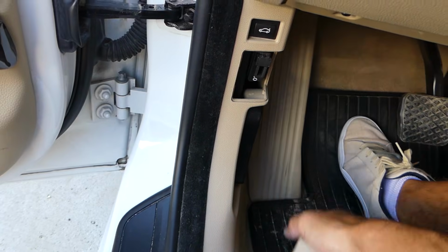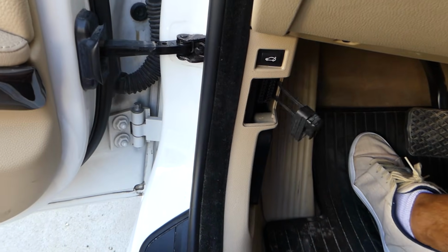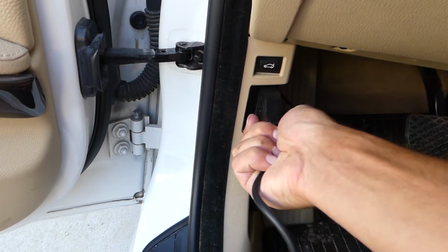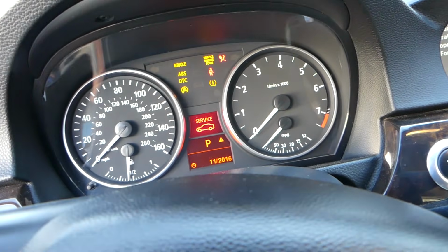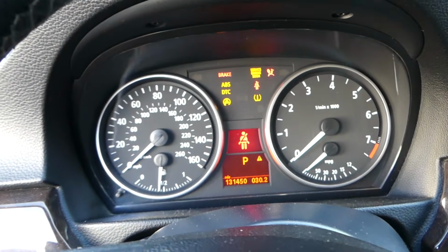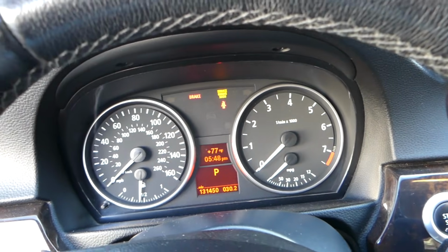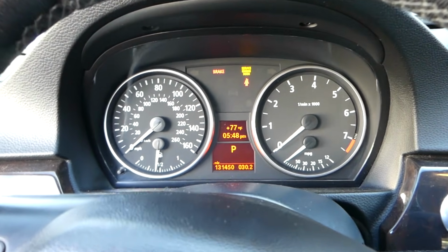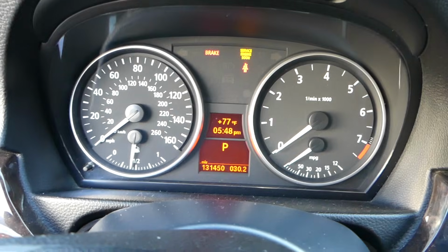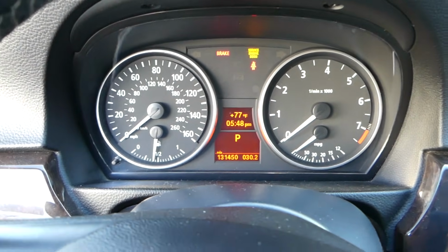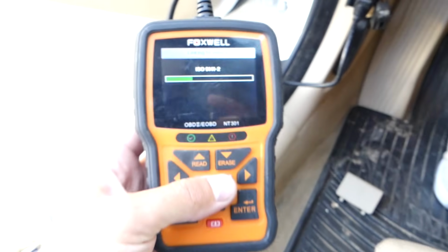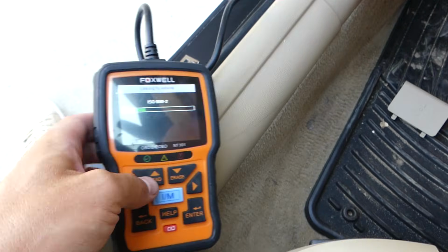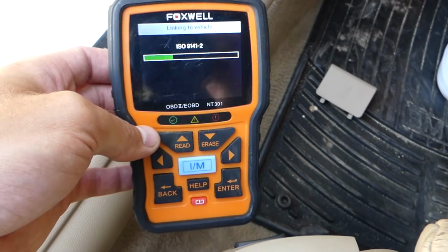So I'm going to go ahead, connect the OBD reader quick, and I'm going to reset all the codes now. Okay, we have to have the ignition on for that without the engine running. Okay, perfect. And see guys if the code will come back. So we'll definitely keep you updated on that. We're going to go ahead and drive it, and before we finish the video we'll let you know if that worked for us or if it didn't. Hopefully it will. All the tools and parts that we use guys will be listed in the description of the video below.